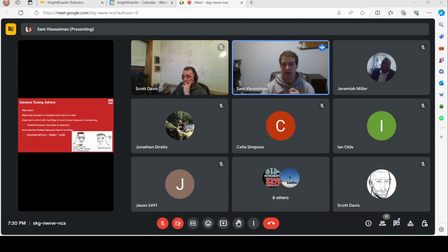I guess I mentioned this before. Alignment with April tags is challenging, and sometimes you just have to go slow because of camera lag. One of the ways you can maybe help with that is turning down the resolution and cranking up the frame rate on your camera. But of course, you're going to lose distance and accuracy. And so really, that's all just a big tuning experiment. And if you really want to get more accurate than that, you might have to look at a different way of tracking your position in space, rather than just looking at your tag and saying, I'm off 5 degrees, therefore adjust.